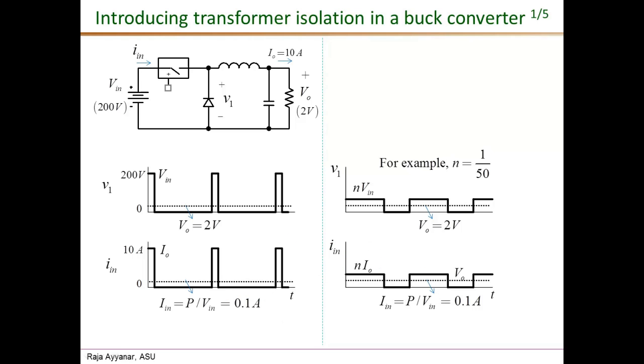Okay, and notice that the input current IN is the same as the switch current as well. So therefore, this would be the switch current waveform, and you can clearly see that we have already solved the two major disadvantages of the non-isolated version. The first one was the total switch VA rating. So the switch now handles only a peak current of 10 over 50, 1/50th of the original case. So that reduces the total VA rating of the switch.